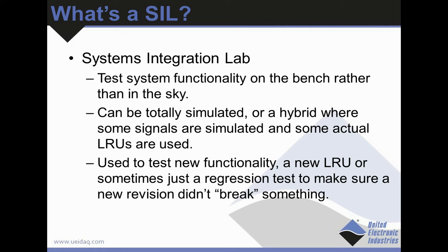Maybe not everyone is familiar with the term SIL, but Systems Integration Lab. And the idea of a systems integration lab is to allow you to test the system functionality on the bench or in a safe location rather than having to try things in the air. In a real aircraft, you don't want to try a failure for the first time and see that it turns out to be catastrophic.